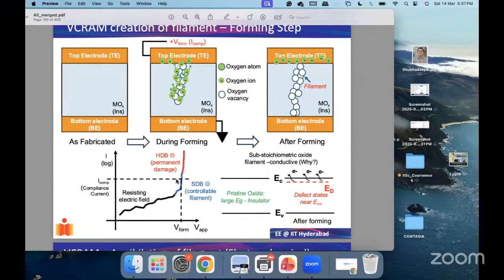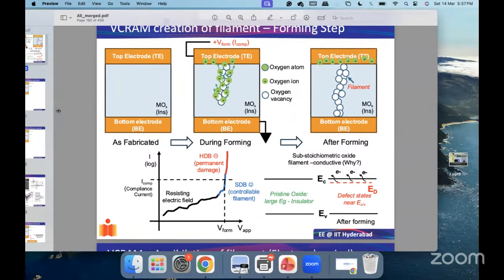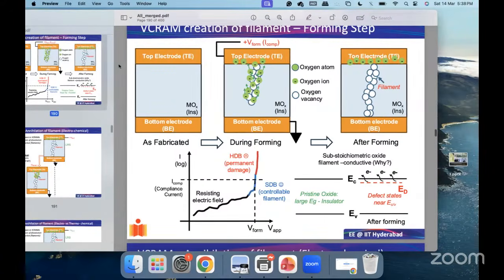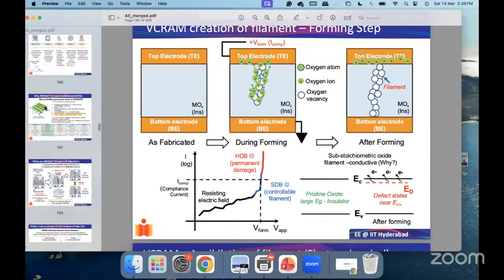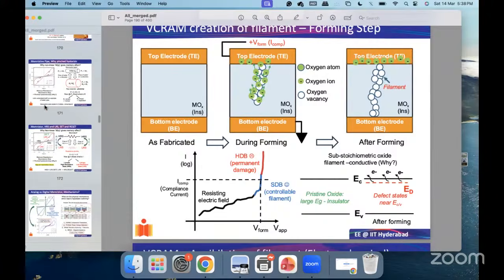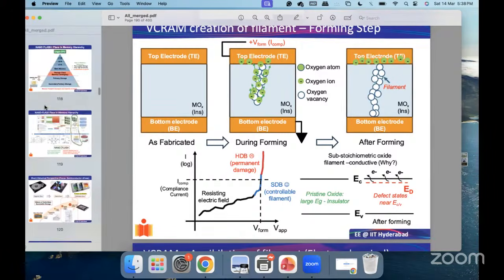During SRAM operations, when we are calculating margins for read and write, we saw that at different corner configurations, like FS or SF or FS global or SF global, generally the trend is that the read margin is worst at FS, and the write margin is worst at SF. So what should be the difference between FS and FS global corner process, and similarly SF and SF global?